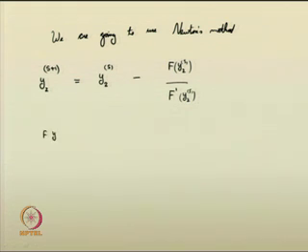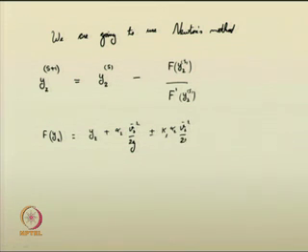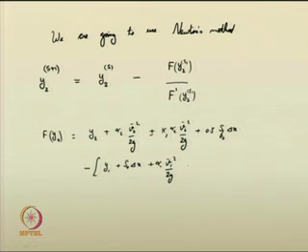Now, how are you going to write f of y2? F of y2 is nothing but y2 plus alpha 2 v2 squared by 2g plus or minus KL alpha 2 v2 squared by 2g plus 0.5 SF2 del x, minus y1 plus S0 del x plus alpha 1 v1 squared by 2g minus 0.5 SF1, then plus or minus KL alpha 1 v1 squared by 2g.